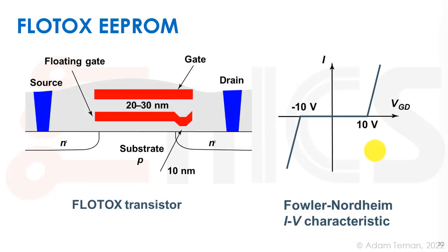And the next invention is the EEPROM, which is the electronically erasable and programmable read-only memory. In this case, we take the same type of structure, so we have the floating gate, but there's a reduction on the side of the floating gate, which makes a really close, thin oxide that overlaps the drain part of the transistor. And that enables us to apply Fowler-Nordheim tunneling to move the charge that we got stuck on here off of that.